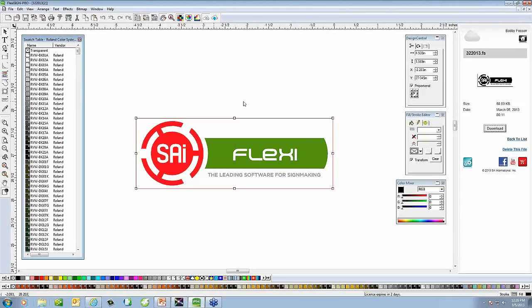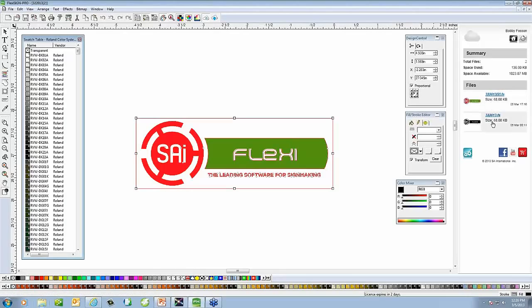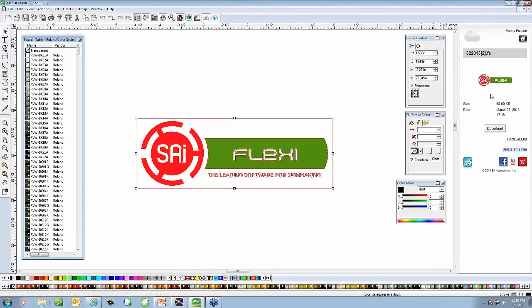And then from there, if again you want to save it to the file, we can do that as well. So what we're going to do is select this job here. I'm going to choose to archive this file, which they have a small icon right up here at the top in Flexi Cloud that says Archive to Cloud. So I can click on this, and then at that point, it's automatically uploaded that file where now I have both of them in here. See the black one that we originally started with, the color object that we have here. You can also manage these files simply by clicking on them. So if I don't need this anymore, I click delete. It's now off your server, and you've now opened up that file space for future use.